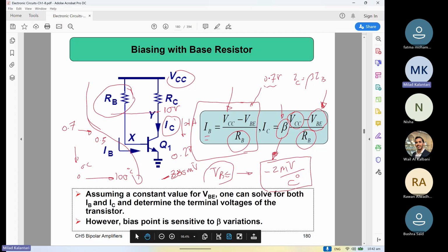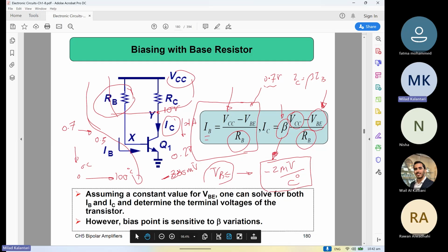But I just ignored the top circuit. I'm just thinking about the device, right? Let's say the VCE, the collector emitter voltage, is 10 volt, and then there is a current passing through the device, which the value is 0.1 amp. What is the power dissipated inside the device? How much?